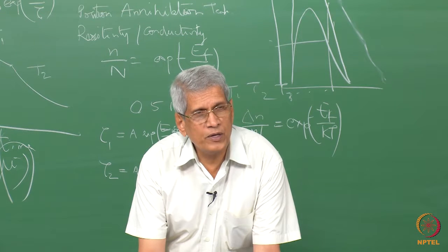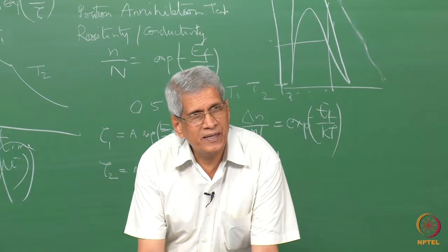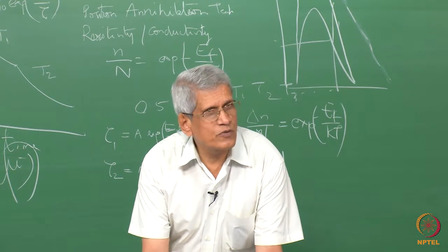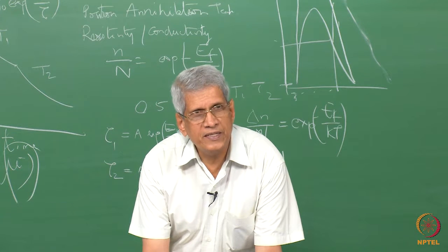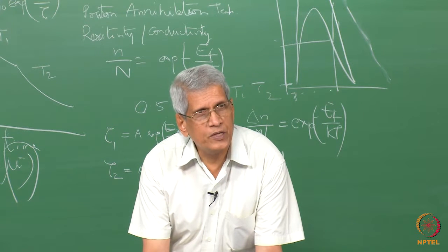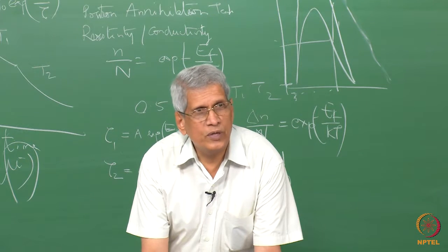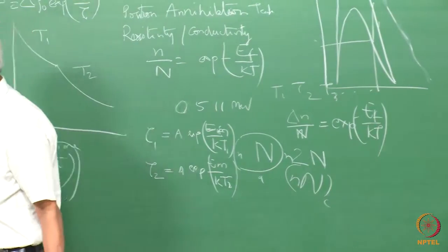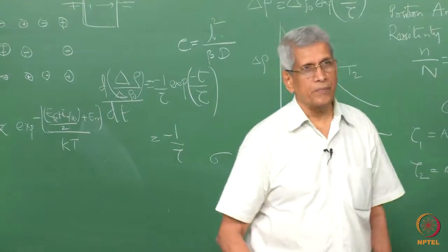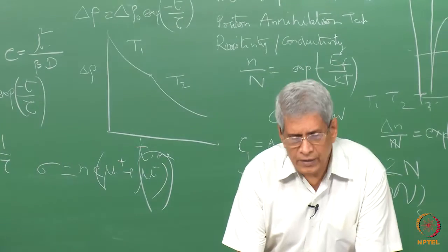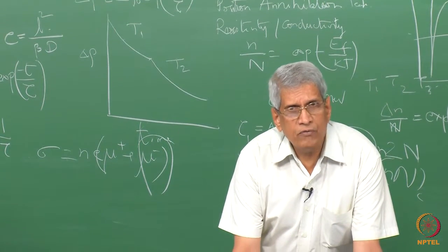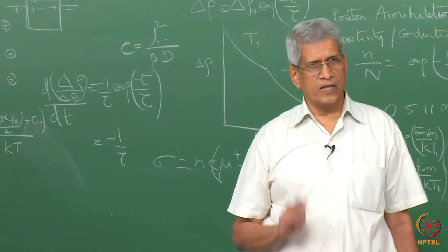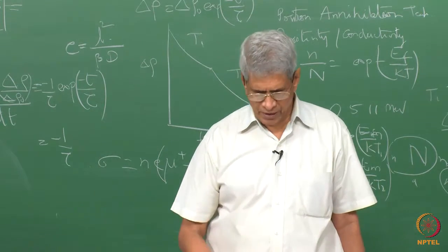Because essentially what we are finding out is the defect concentration at various temperatures, and at lower temperatures the defect concentration is fixed. So, only the mobility decides how the conductivity is going to vary. So, that gives information only about the migration, because when the concentration of the defects is constant, this part will not come into the picture. Okay. So, using this sort of a plot, we can get information about both the migration energy as well as the formation energy. All this information we can get.